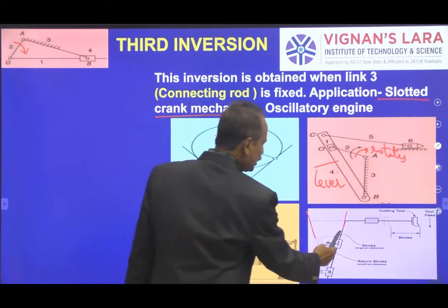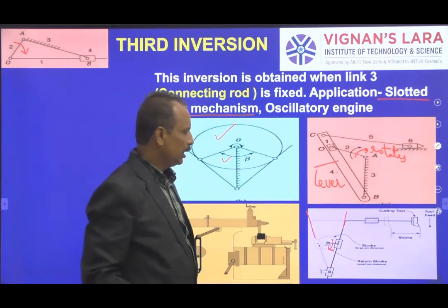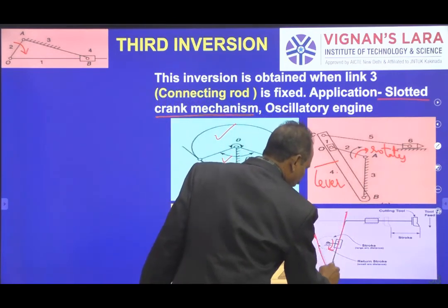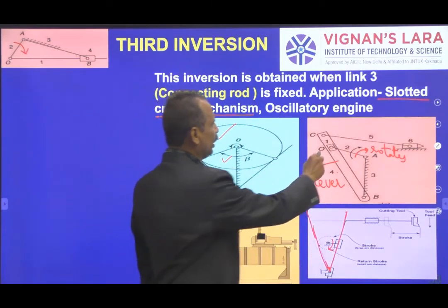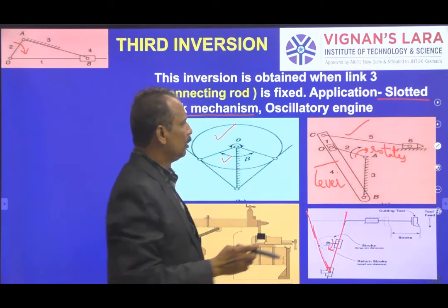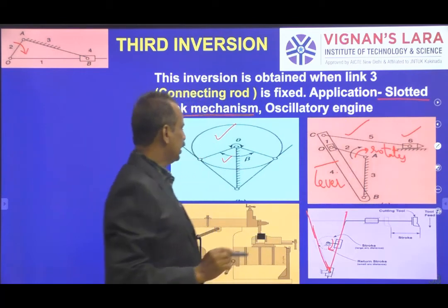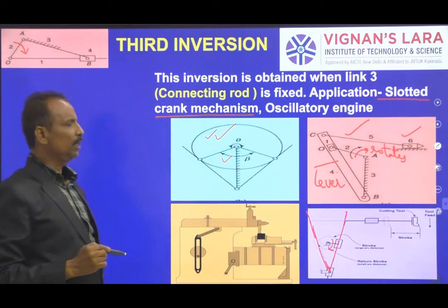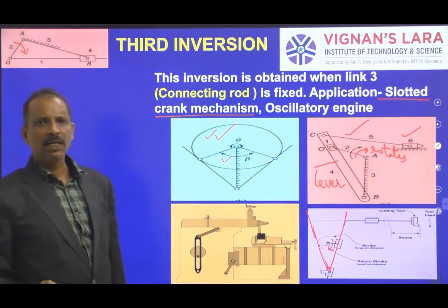So this rotation of this crank is causing an oscillation of this lever between these two positions. The end of the lever is connected to another link or a coupler which causes the reciprocation of the tool. Okay, so here also the same thing, forward stroke will be completed in more time and return stroke will be completed in less time.